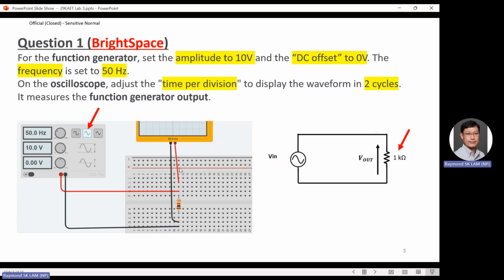You look at the red wire, you go this way, go to the copper thread, and then it is connected to the function generator positive terminal. And then the black wire, if you trace along here, you will go here, okay? Because these 5 holes are connected, right? And then finally, the black cable is measuring the negative terminal of the function generator.